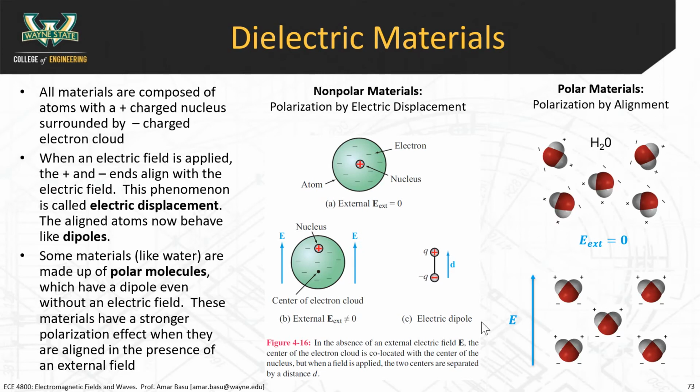So water can't even support an electric field because it behaves more like a conductor. Yeah, Siva made a good point. DI water is the one that actually behaves like a dielectric. And if you do get pure DI water, the dielectric constant for DI water is something like 80. It's very, very high, whereas most materials have relative dielectric constants between 1 and 5.